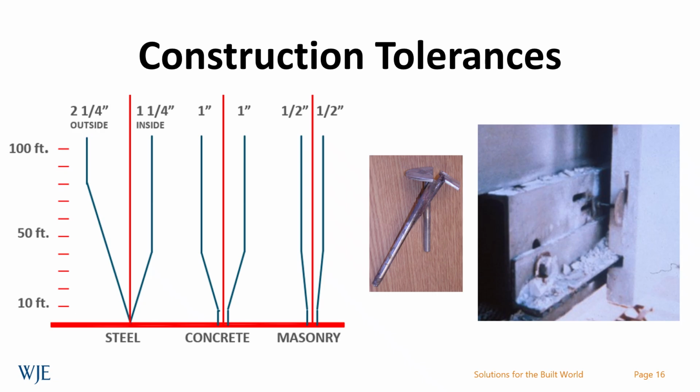Another consideration in mid-century facade systems is accommodation of tolerances. Generally, particularly with masonry systems, the tolerances are much tighter than the structural system behind it, whether it's steel, concrete, or masonry itself. Those tolerances have to be accommodated in the detailing of the system. And while those were understood at some basic level during the early part of the mid-century, how that was accomplished was also done through some fairly extraordinary means in terms of field modifications made by the contractors. And you can see a couple of examples of those here.